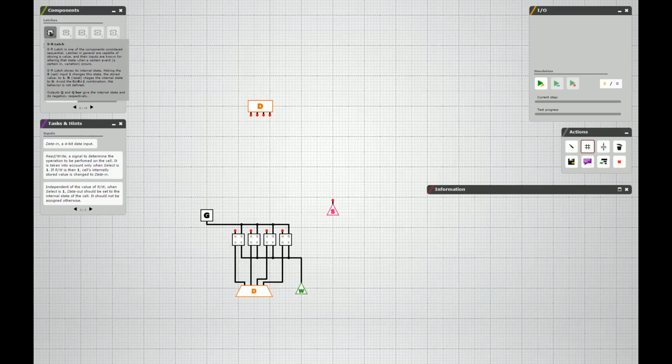And what is that gate? It's not SR latches, because with SR latches, the inputs S and R define what its contents contain, not S defines content and R decides whether it gets let through. Could we do it with another set of these memory cells? We could, probably. We would just make enable be S and pass this data from Q through to the new D, and then that would output it. But that's not going to work because we don't have any more of them. It would be a shortcut, and maybe not the right way to design a memory cell. It would be almost like a buffer, where you're buffering the memory. So let's go back to our other gates and see what we have.